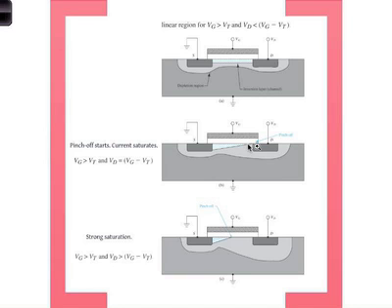Okay, which means that you will end up having a pinch off of the channel. It's a different physical mechanism, but you will have the same result. Okay? You will reduce the carrier concentration here, and this here it will be maintained. At some point, the current pinches off, and you reach saturation, and that's when the pinch off starts, current saturates, and that's the situation. Of course, the gate has to be greater than threshold because you need to have some sort of channel, and the drain voltage is now gate VG minus VT, which is right there.